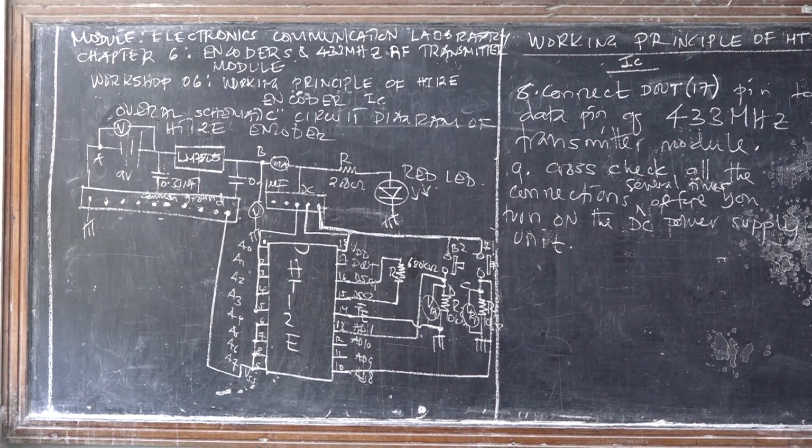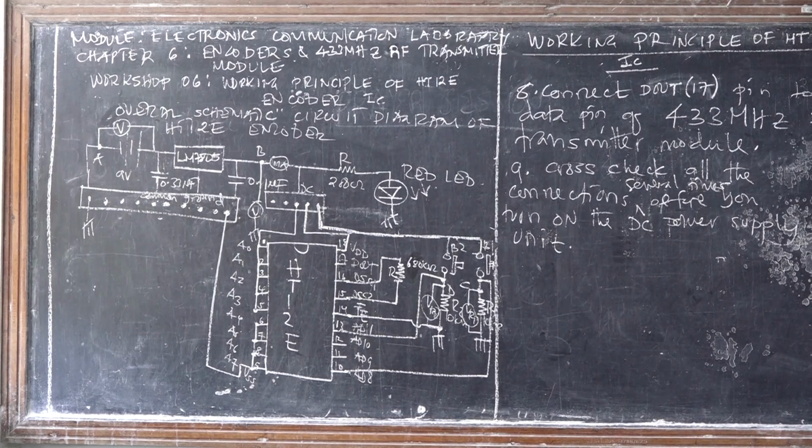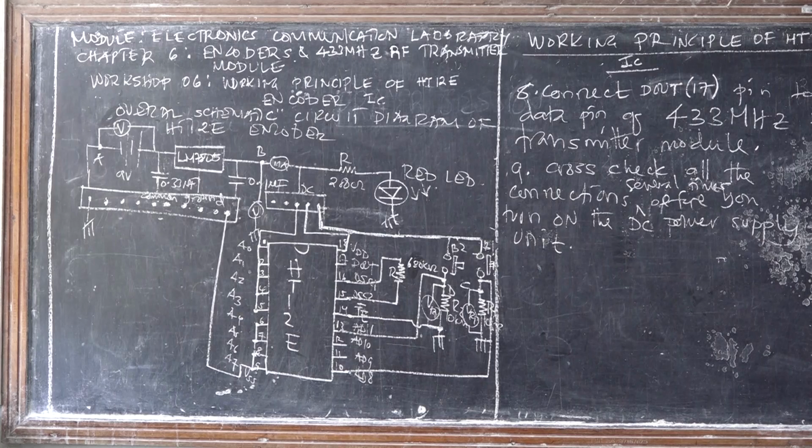It has a built-in oscillator, but it also needs an external oscillator that we call the external crystal oscillator. In most cases, you use an 8 megahertz crystal oscillator or a 16 megahertz crystal oscillator. In just a few cases the microcontroller has to be connected with a 32 megahertz crystal oscillator. But for this case, we don't need a crystal oscillator. They just need a fixed linear resistor. That's all.